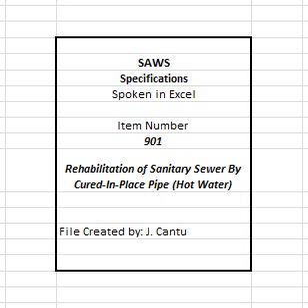6. Map that legibly shows proposed liner insertion location(s), construction staging area(s), and bypass pump and piping locations. 7. Traffic control plan, if required, in accordance with City of San Antonio Street Cut Policy or TxDOT traffic coordination, TxDOT. 8. Bypass pumping plan in accordance with specification item number 865, Bypass Pumping Small Diameter Sanitary Sewer, or number 864, Bypass Pumping Large Diameter Sanitary Sewer.